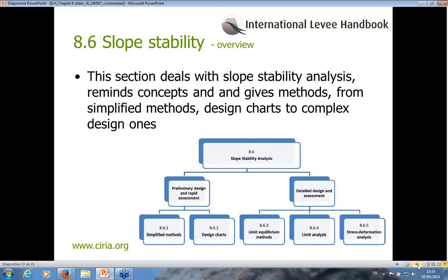Limit equilibrium methods, which are still the most used methods in practice, are detailed. Analytical methods like the infinite slope model, the Swedish method, and slice methods such as Fellenius, Bishop, Spencer, Morgenstern-Price, Janbu, etc., and perturbation methods are also described, and their equivalence with the slice methods is discussed. Limit analysis methods are also briefly reviewed. Their principles and main assumptions with regard to the previous approaches are discussed.